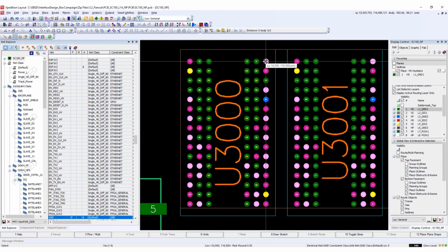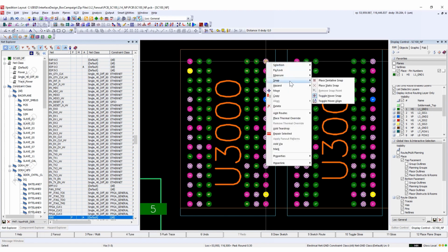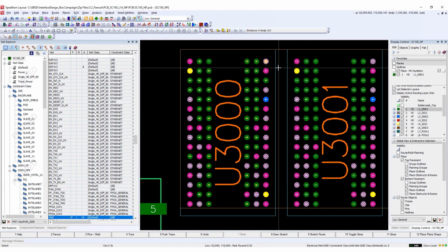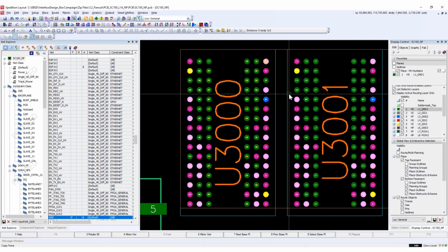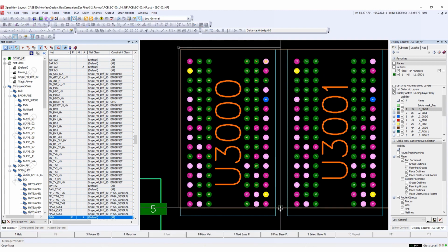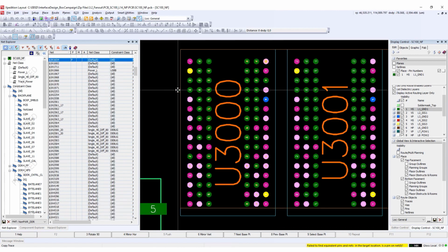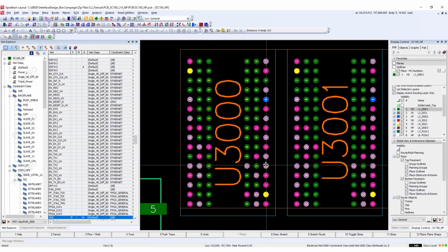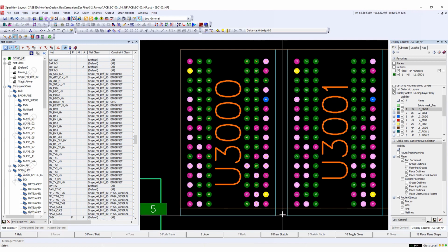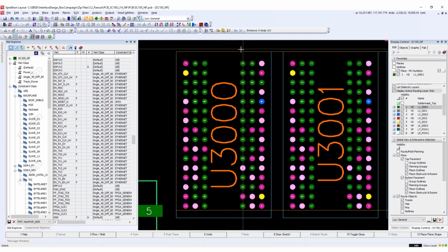Now I can use the copy circuit functionality to paste this via to all the other ground pins. So turning hover snap off, I'll select this via and use the copy command, and then with my net filter still enabled, area select the rest of the pins. And we can now see that the via has been placed on the remaining ground pins. So the via and pad fanouts for the first DDR chip have now been completed.